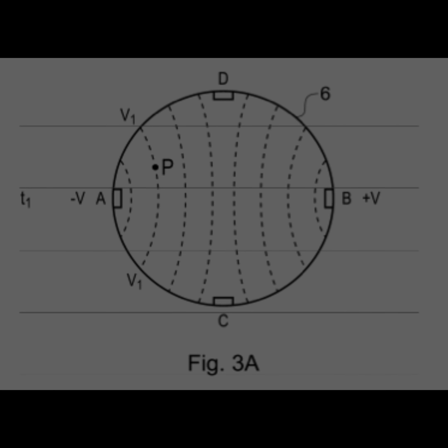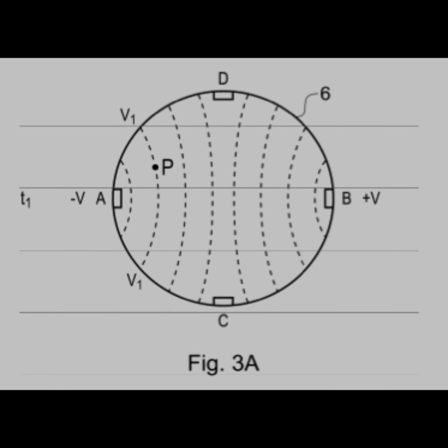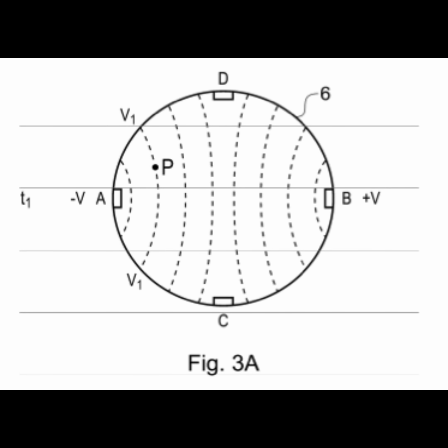Figure 4 shows another joystick 11, which is a second embodiment of the invention. This joystick has a flat support 12 on which a resistive layer 16 is coated or glued, a cover 13, and a telescopic actuator 14. The actuator comprises a conductive element 18 at one of its ends and a spring 20, which urges the conductive element 18 onto the resistive layer 16. This ensures that the conductive element 18 is in contact with the resistive layer 16 for all positions of the actuator. All other parts of the joystick correspond to those of the first embodiment.